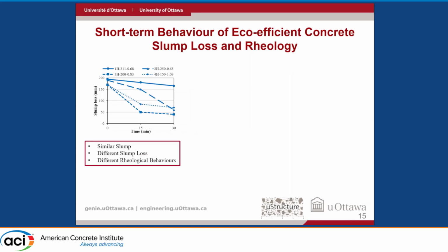Besides that, another thing we have done, just to check, because we thought that that might have been an issue, was the slump loss over time. This is very important, practically speaking, for concrete suppliers. And we could see that if you decrease the amount of cement, unfortunately, we're going to have a higher loss, and of course, increasing the amount of fillers as a function of time. So this is something that we will need to pay attention to if we go towards that perspective. But more importantly, that is slump.